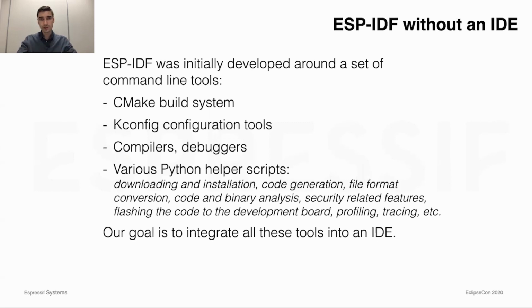So what's inside ESP-IDF? ESP-IDF is built around a set of command line tools, such as the CMake build system and Kconfig configuration tools. It's the same tool set that is used in the Linux kernel and other real-time operating system projects, such as NuttX and Zephyr, for configuration. We use the GCC compiler, the GNU debugger, and also a multitude of Python scripts,